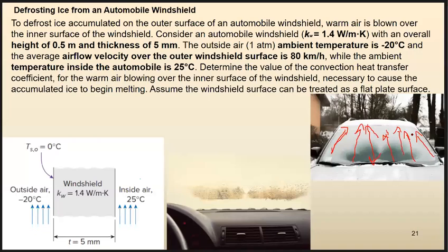While the ambient temperature inside the automobile is 25 degrees Celsius. What is the value of the convection heat transfer coefficient for the warm air blowing over the inner surface of the windshield necessary to cause the accumulated ice to begin melting?